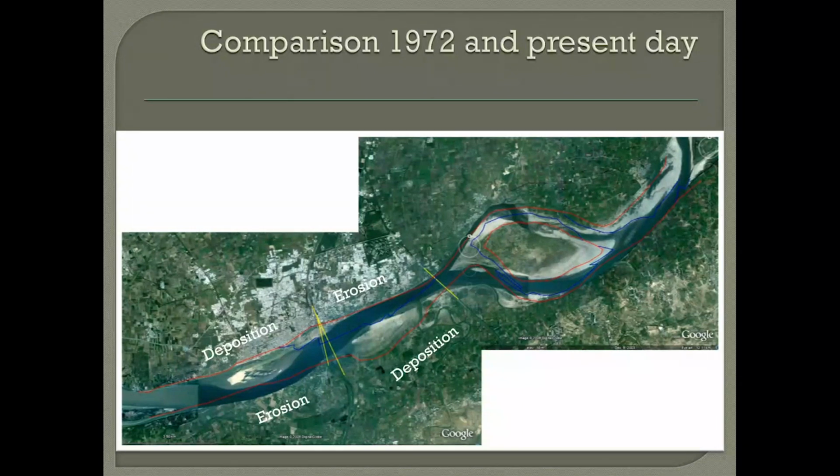What is the trouble? Because this Bharuch city is around 40-45 kilometers inland from the sea, and all the water what you see here on the river is saline water, and Bharuch city is already facing saline water intrusion from the river. So the water below this Bharuch city where we make a borewell is now getting more and more saline. So I told the collector, if you are going to construct a canal and if it survives, it is going to be more dangerous for people around Bharuch city.